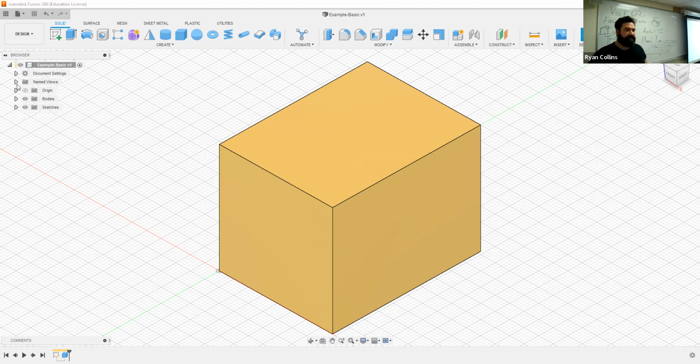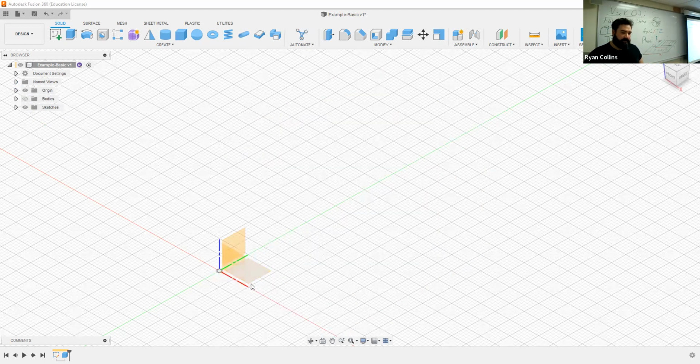Next thing down, your views. That's just, again, the top right. You can rename them if you like. Origin, there's a little eyeball next to it that's grayed out, or rather the other one are with a slash through it. The other ones are solid. The origin comes up. That's what I originally built my cube on, right there in the center. Let me hide that by toggling the eyeball. There's my origin right in the center, has the axes and the correlating planes that you can see through.